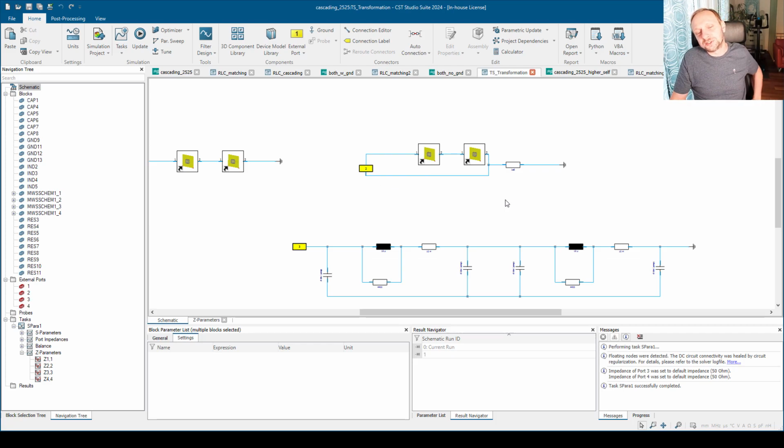However, this works because of one reason. This works because the capacitance to ground is dominating. What I said about the self-capacitance of the inductor: it's not the self-capacitance of the inductor. We see mainly the capacitance of the traces to ground.